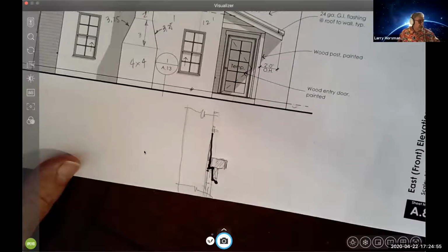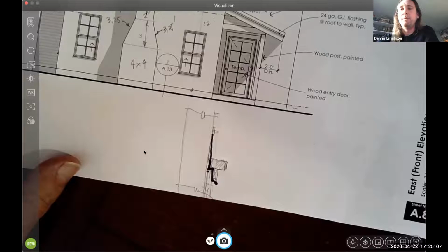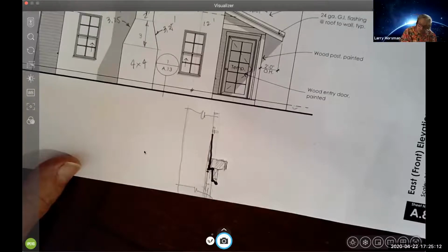So it's a pretty detail, and it breaks up the line and gives you some definition, and it's very architectural. The problem is that's where the leaks come from later. You could cut a drip into that one piece of molding too, the upper portion. Yeah, I could put a little kerf or something. So right there, I could.